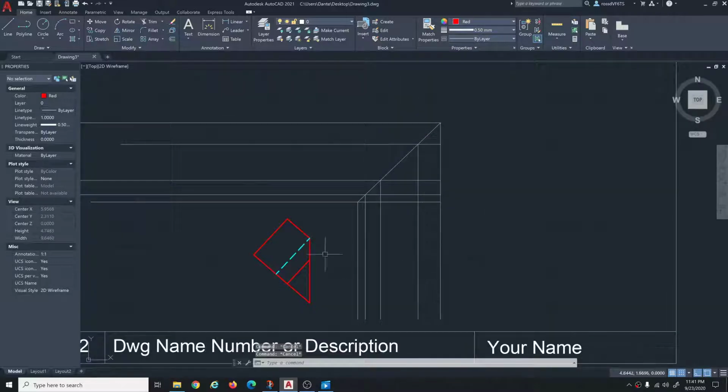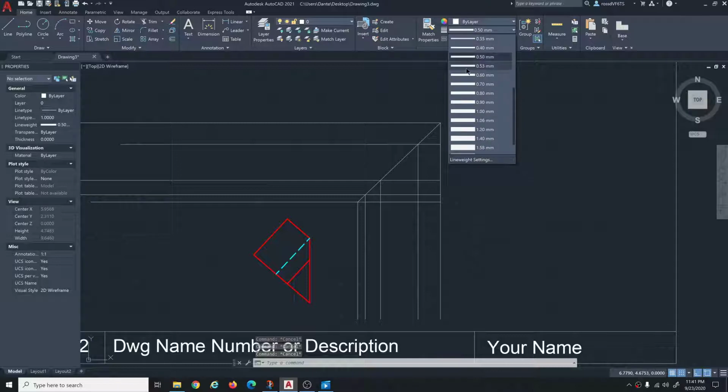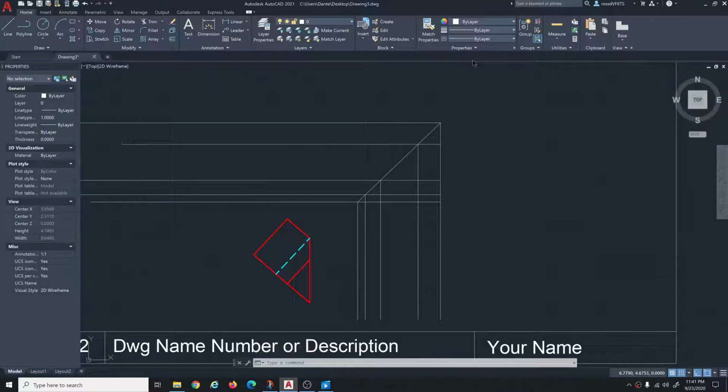So we got to go back to plain old lines here, POLs, plain old lines. Then start taking each one of these points, and you could snap perp, or you could just with ortho draw past. I'll go ahead and snap perp. Make sure you don't miss any of these guys. Okay, this line here,